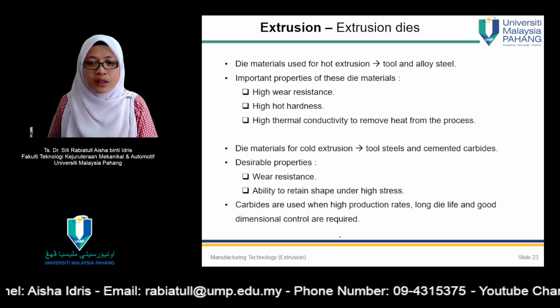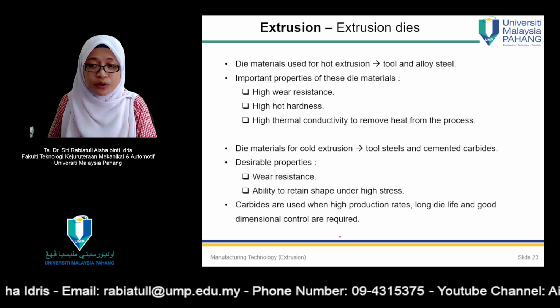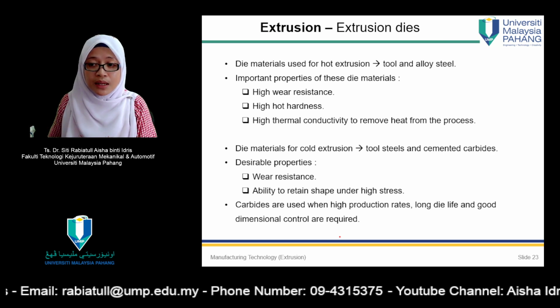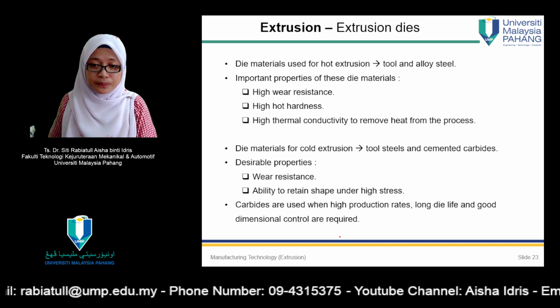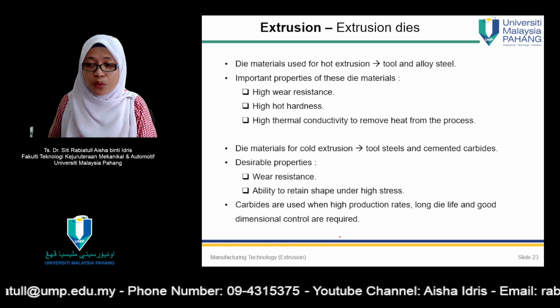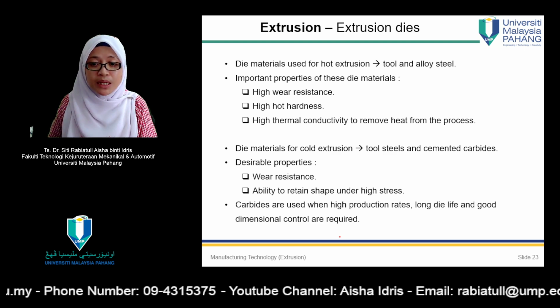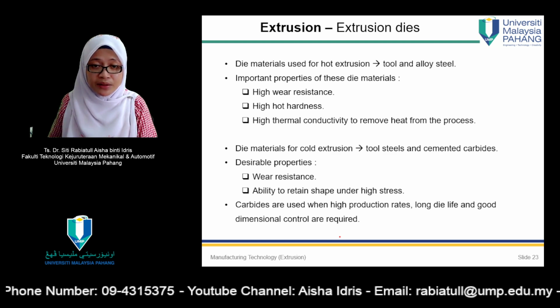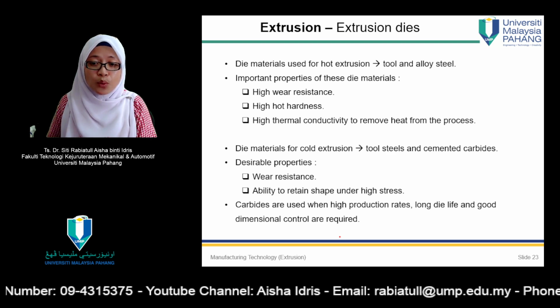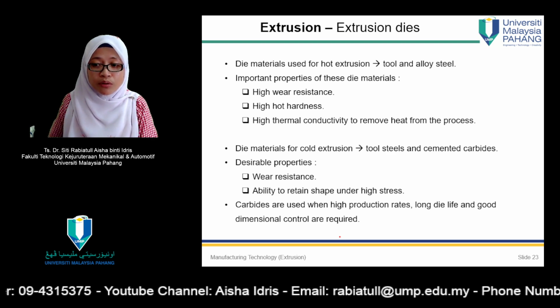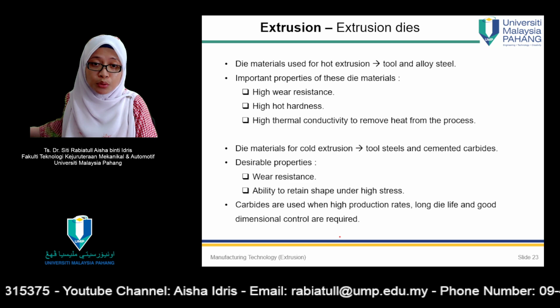Meanwhile, for die materials for cold extrusion, normally tool steels and cemented carbides are used. The properties for those materials are wear resistance and the ability to retain shape under high stress. Carbides are used when high production rates, long die life, and good dimensional control are required.